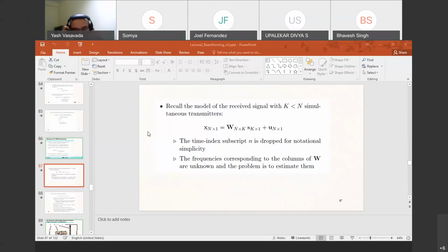And so that is a variant of the MUSIC technique which is called root MUSIC. Basically, you are trying to determine the roots of this polynomial equation. If you can solve the polynomial equation, and now there are many good numerical solvers, you directly get the answers, the locations of the frequencies of interest. So root MUSIC allows you to do away with putting up those signal processors. Although you will have to do a lot of number crunching in the software, you don't need corresponding hardware for that.